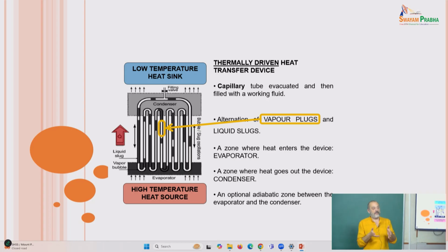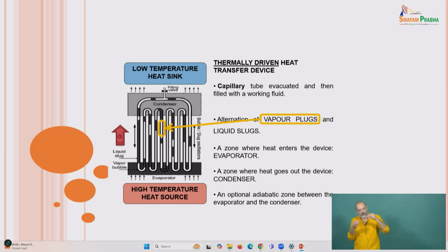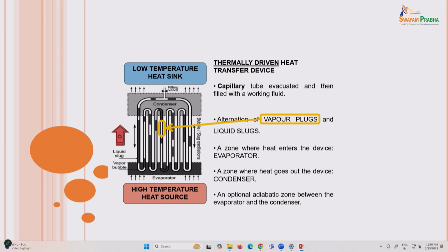The vapor quality at the very beginning is not 0, it's not 1, but it's very small. So we are going to have vapor inside, okay? It can be 0.05, something like that. But we have a vapor quality, so we have a two-phase system. So what is happening, if the system is capillary, is a movement of the liquid slug due to the expansion of the vapor, okay?